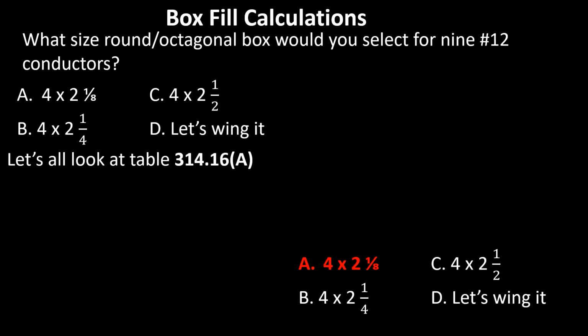Now let's go over to the next large section of that table there. Across the black bold heading, it says maximum number of conductors. Okay, and they're arranged by wire size. So if you go down, just down to the next cross column, you see 18, 16, 14, 12, 10, 8, 6. Those are the AWG. That's the size wire. And then if you look down underneath that, that is the conductor count.